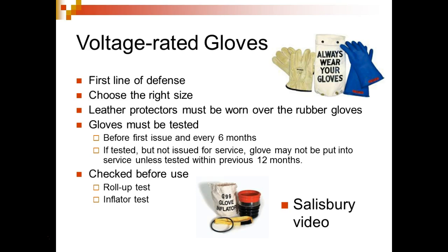Choose the right size. Leather protectors must be worn over rubber gloves. Gloves must be tested before first use and every 6 months. We had a company, I don't know if it's still out there, it was on Lorna Road, I can't remember the name of the company. But they made a lot of high voltage test equipment, and they would test rubber gloves.